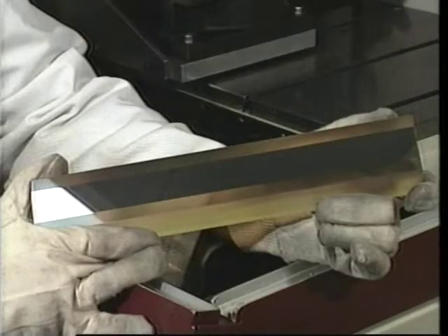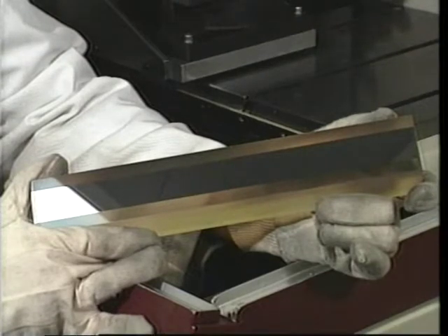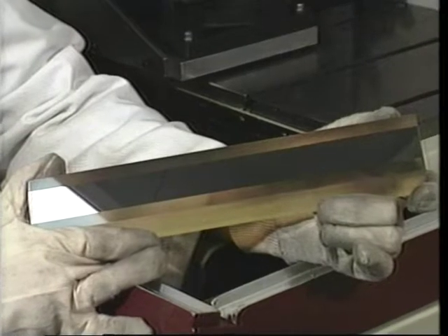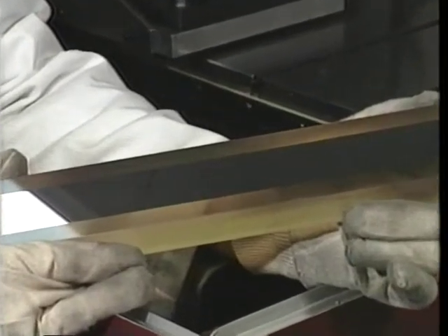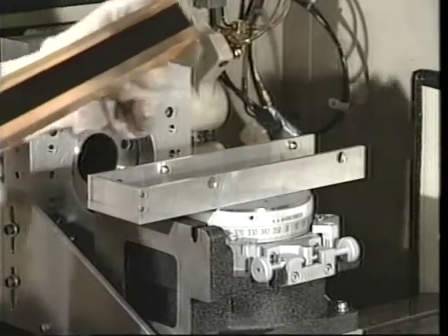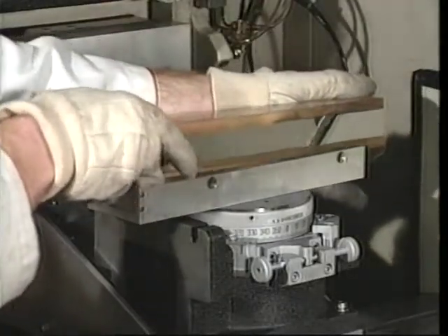As you recall from a previous lab, Zerodur is a glass material with a very low coefficient of thermal expansion, making it a very attractive material for high-precision applications requiring dimensional stability. The reference surface of the straight edge has been ground, lapped, and polished to be both smooth and flat. The error in the straight edge is specified as 45 nanometers over the 300 millimeters of length. The reference surface has been metal plated to facilitate use with a capacitance gauge. The optical straight edge is carefully placed in the cradle.